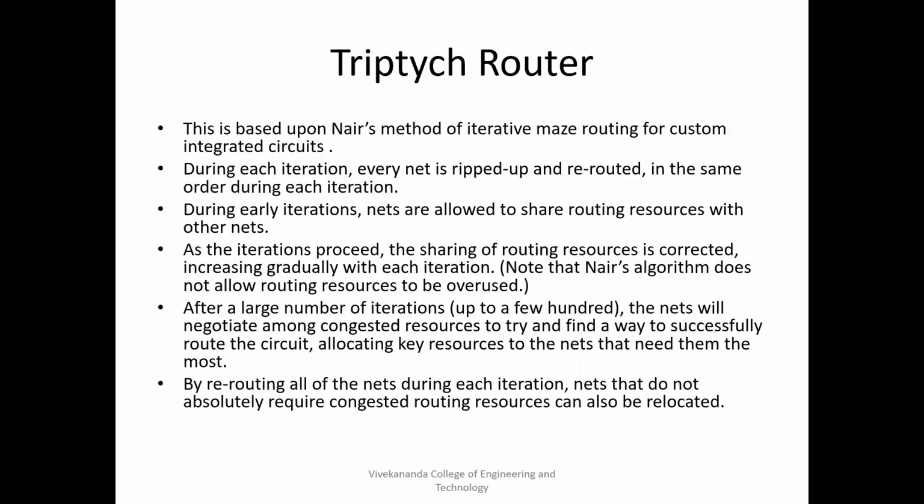As the iteration process proceeds, the sharing of the routing resources is corrected, increasing gradually with each iteration. After a large number of iterations, the nets will negotiate among the congested resources to try and find a way to successfully route the circuit, allotting key resources to the nets that need them the most.